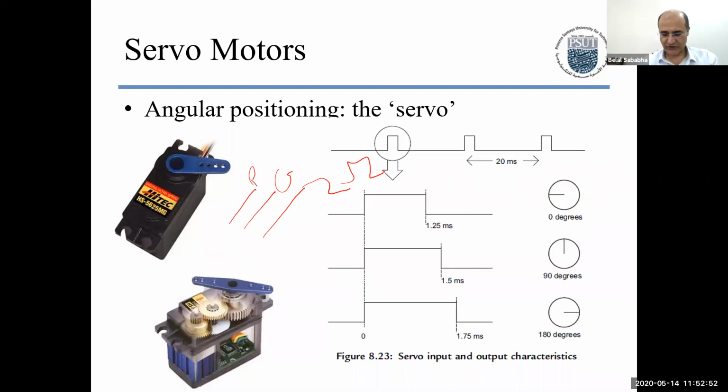It's not a sensor, it's an actuator, right? So you give it a command for what angle you want it to go. And of course some of these servo motors are 360, meaning they do a full rotation cycle. Okay, I'll talk about them. But these kinds of motors are usually used to control angle or maybe rotation, and you have feedback.